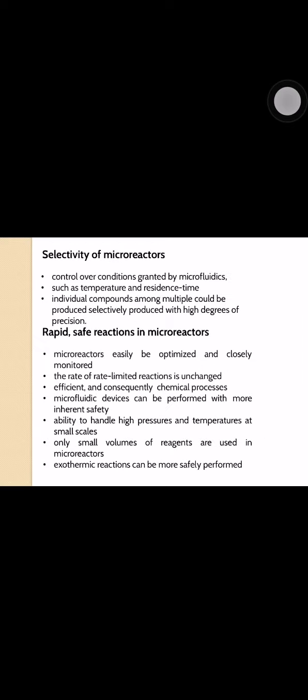And the third advantage of microfluidics: rapid, safe reaction in microreactors. Microreactors can more easily be optimized and closely monitored to not run any longer than is necessary to reach the reaction endpoint, and are accordingly reported to have greater space-time yields. Thus, even if the rate limiting reaction is unchanged, microfluidic reactors will allow for more efficient and consequently more rapid chemical processing.